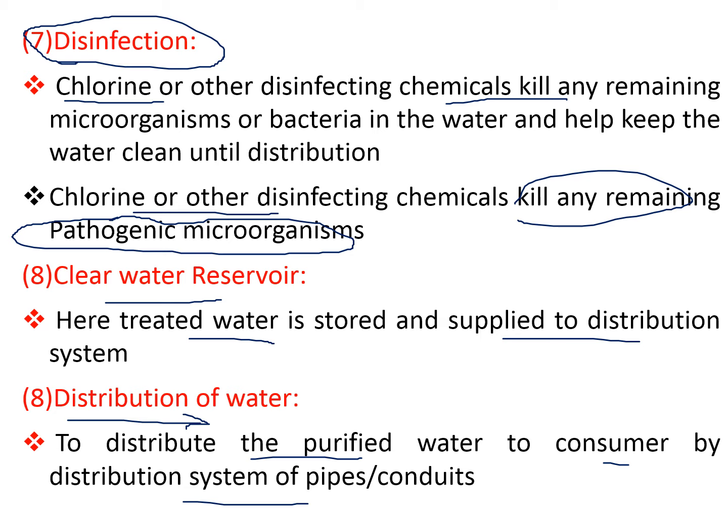to consumers. So when it reaches your house, whatever drinking water standards for different parameters are to be maintained. Generally one parameter which is very important is called residual chlorine. A minimum of 0.2 milligram per liter of residual chlorine has to be present when the water reaches your house. Then you can say that you are safe from the contamination point of view.